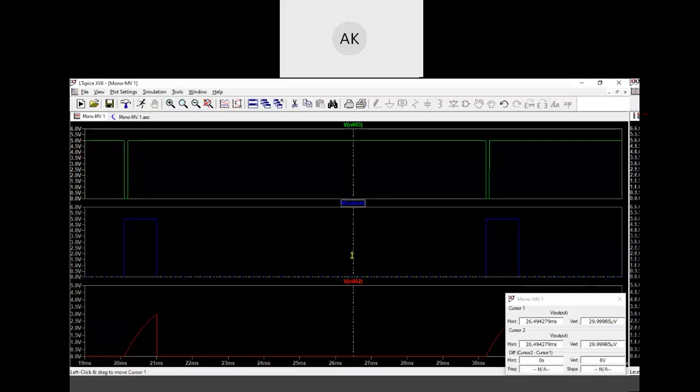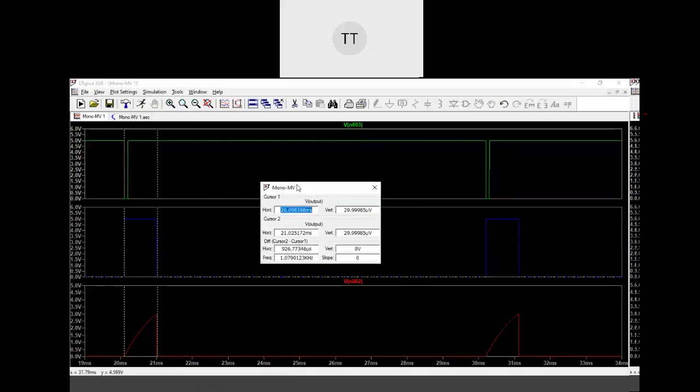As per our RTCT, what is the value of time? That time is supposed to be 916 microseconds. Let us see what the time is. Is the difference almost close to it? Can you see it's almost there, 926?